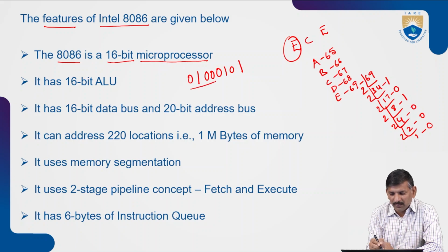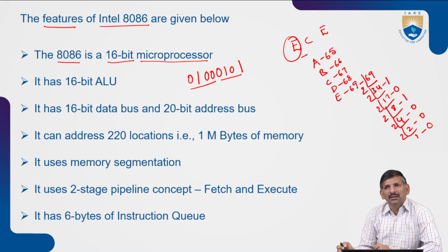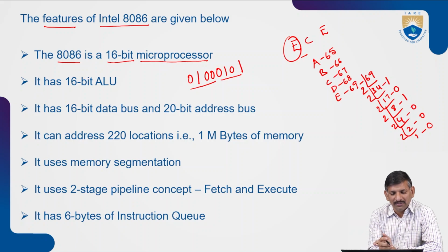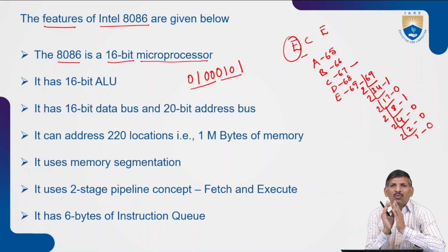So this is the 8-bit information for capital E. In the same manner, each piece of information has some binary number. These binary numbers are accessed as 16-bit information at a time. This is 8-bit information, bits 0 to 7. At the same time, C for the corresponding binary information, like that. At a time, the 8086 microprocessor processes 16-bit information, in one clock cycle.